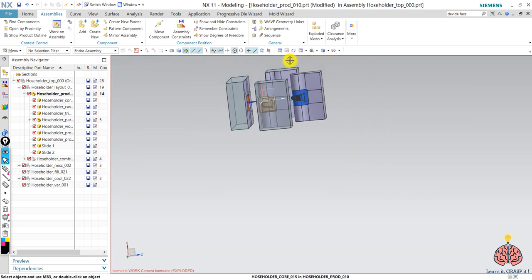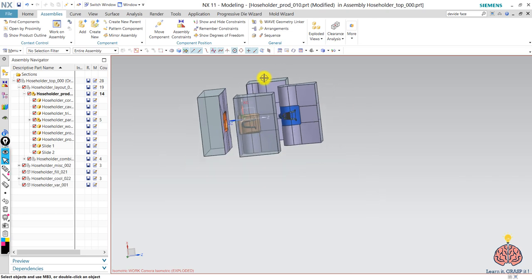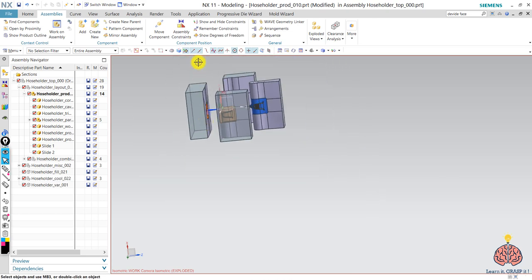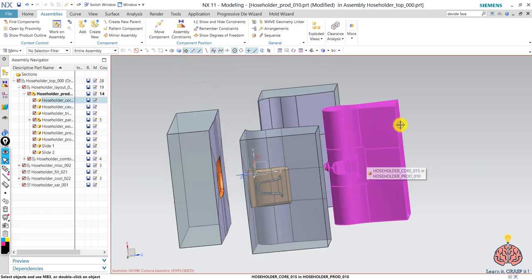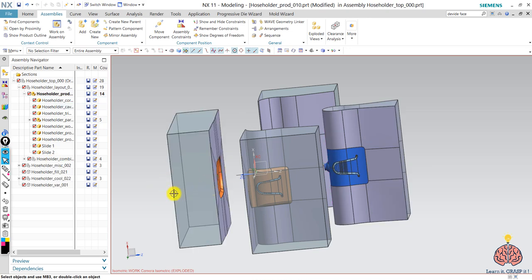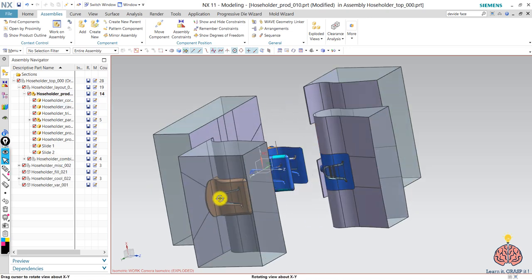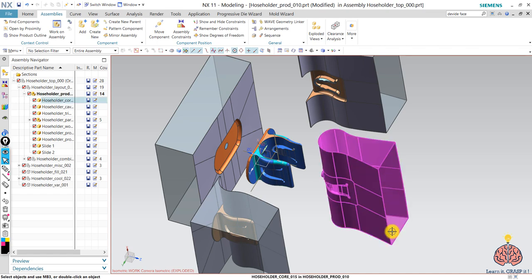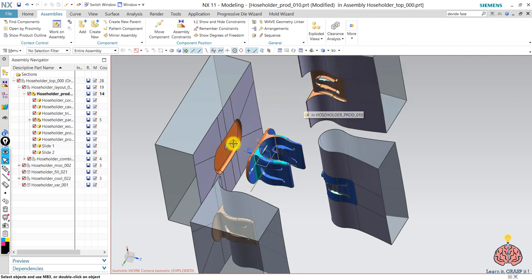This is the mold combination. This is the steady part. This is the moving part. The injection will come from the steady part, of course, and this part, like the core, will get in, and the slides will also get in. If it were actuators, or if it were the sliding pins, whatever, everything will get in place, and then the injection mold will go on.